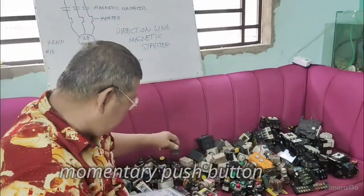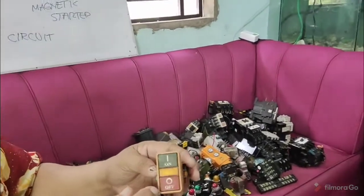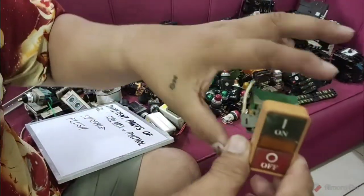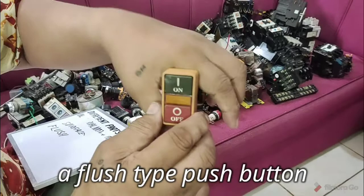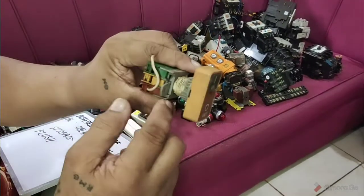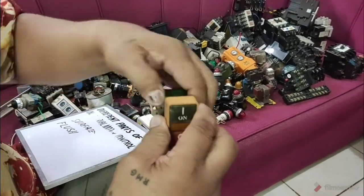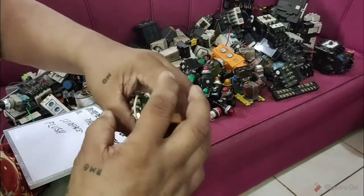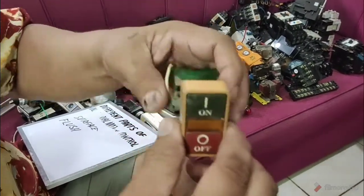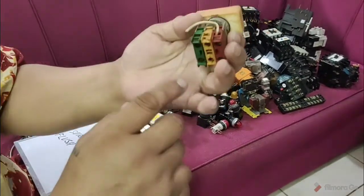Okay, so we have also another one. Look at the push button, a combination of on and off. So this is flush type because you will have a control box, and then this is the one that will come out. So what you will do, you bore a hole, and then you install this. This one, you pull this out, and then you have here the white one, then put that in a hole, and then cover it. Then that is the one that will come out.